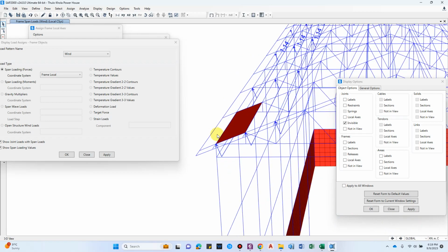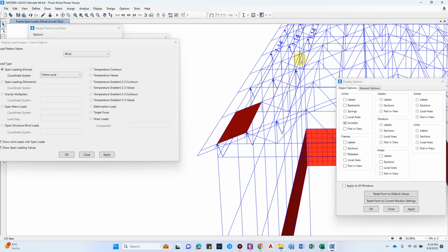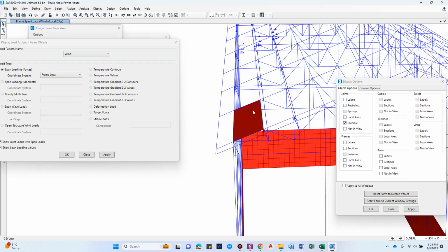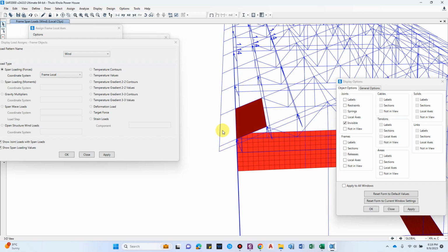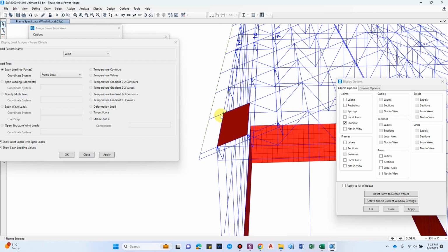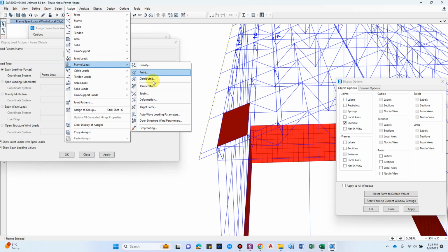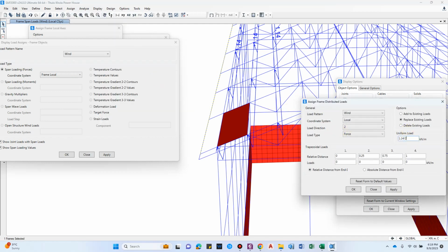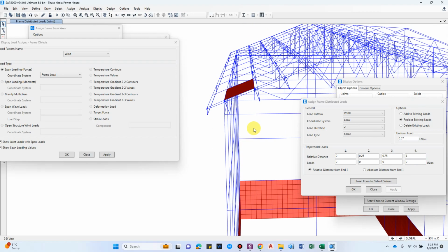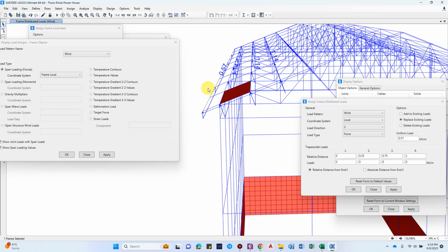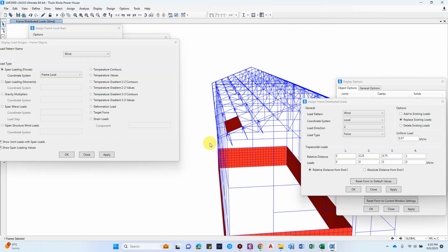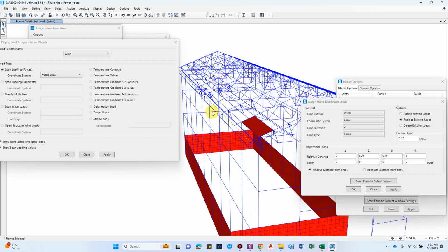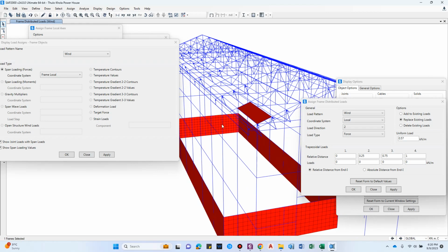And for the purlin at the outer edge, it will be half of the load that is in this purlin, because this purlin shares load from this half area and the half of this area. But for the purlin at the edge, it will simply take half of the load from this CGI sheet. So if it is 1.14, then obviously for this it should be half of the load that we have considered, in this way, right? So also resolve this, that is the angle for the local axis of this frame. So in this way the load for the pitched roof is computed and applied on the model.